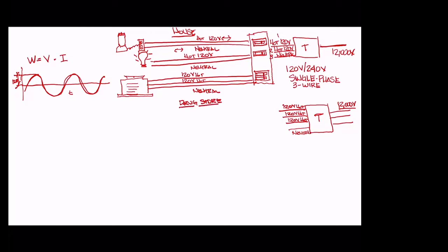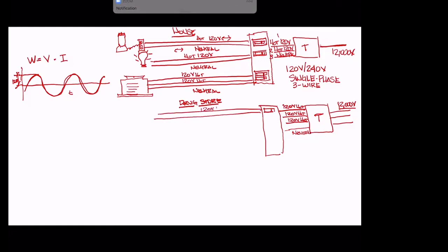All right, for our pharmacy, we're going to have, as you might imagine, another breaker box. And that breaker box is going to do the same thing. It's going to distribute power. It's also called a main. In bigger buildings, it's called sometimes a main panel or main electrical panel. And so we're going to have a circuit here, and that circuit is going to go to the plug loads, the process loads, and it's going to have 120 volt hot wire, and it's going to have a neutral. And the electrons are going to go out this way, and they're going to go through the different electrical receptacles that may be serviced by this particular circuit and back. And if something's plugged in, they're also going to go through the equipment or lighting that's plugged into it.